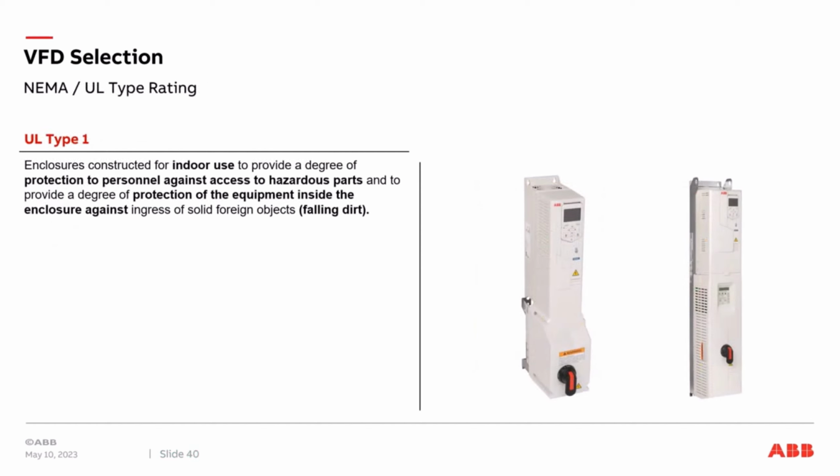First of all, a UL rating is a tested rating. A NEMA rating is something that a company can just self-certify to. So if I'm working out of the garage and I say I'm a NEMA Type 1, it's because I believe that I follow the NEMA regulations and I've never tested it. I believe I'm fine. A UL Type 1 rating means that UL has inspected it.